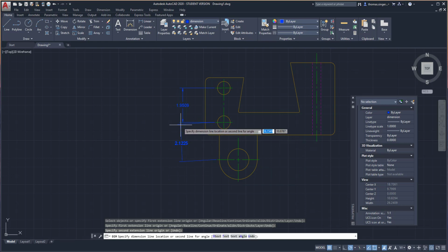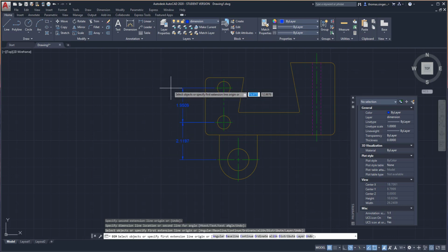And we know that all the dimensions, that's a problem. Notice how angled that is? You want to straighten that up to make sure it's vertical. And I'm actually selecting the endpoint of the other arrowhead, so they purposefully align. But notice that as we have dimensioned, we've got 4 decimal places. Well, that's a lot of decimal places for a basic dimension.